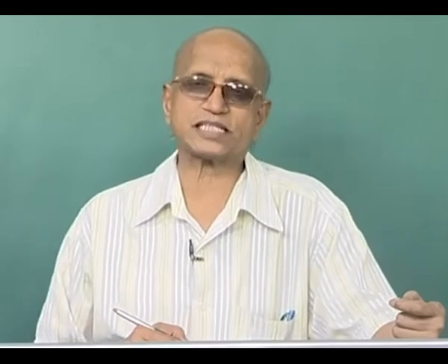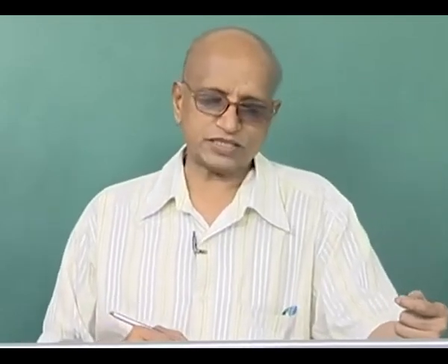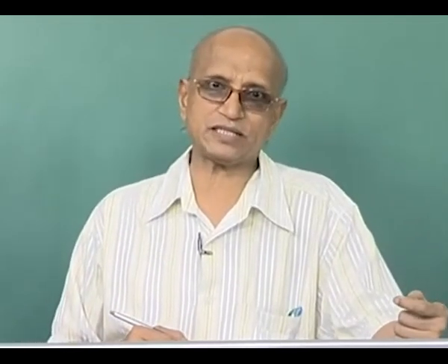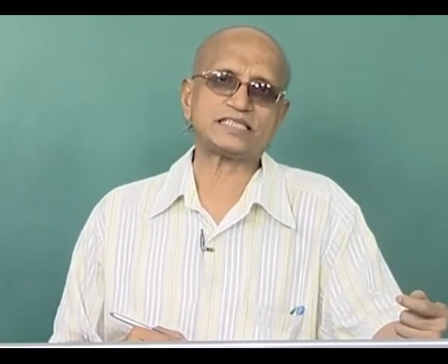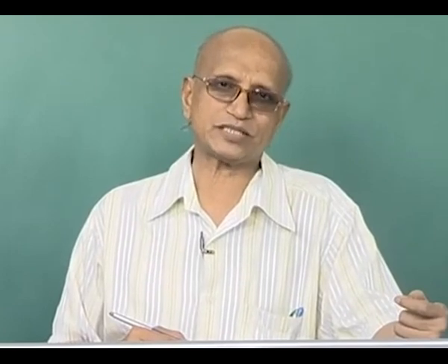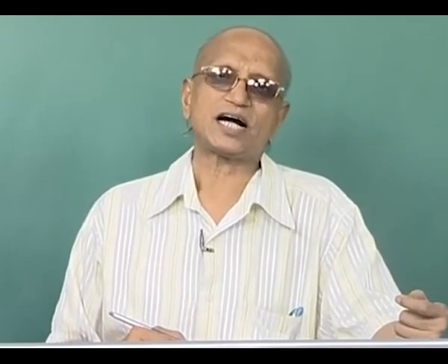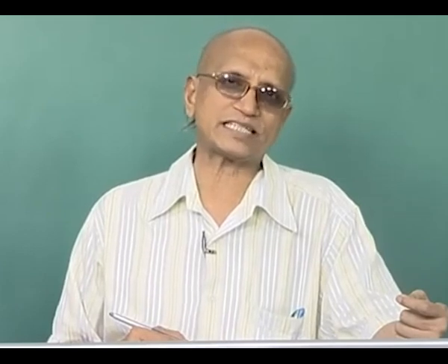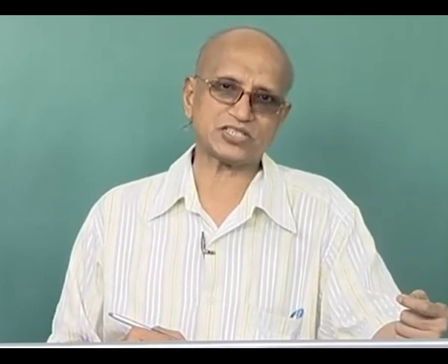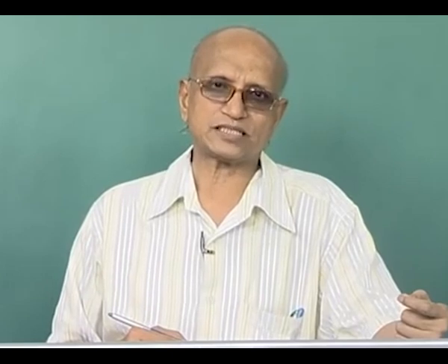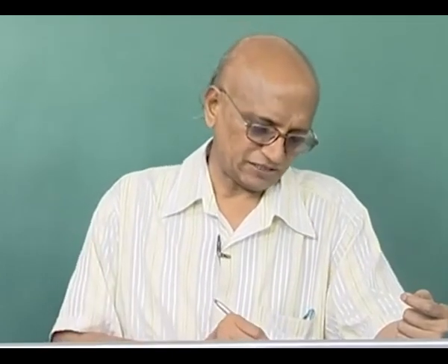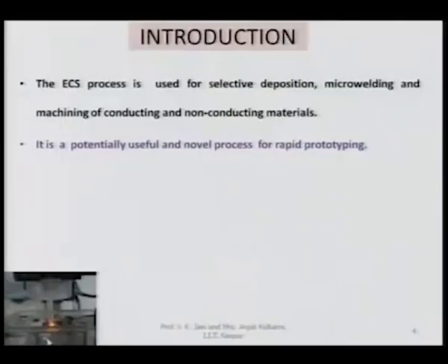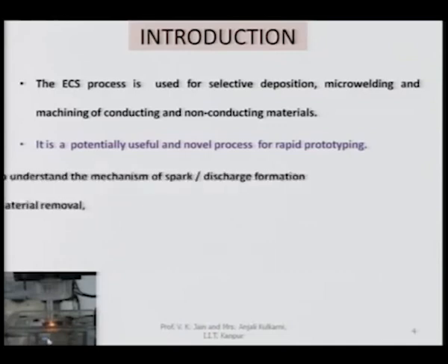So, this process is a unique process which can be used for electrically non-conducting material, and it is a hybrid process, as I will discuss a little later, which combines ECM process and EDM process. Both these ECM and EDM processes are useful only for electrically conducting materials, but the hybridization has led to its utilization for electrically non-conducting materials. It is potentially useful and novel process for rapid prototyping also.